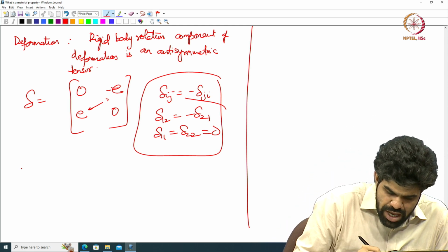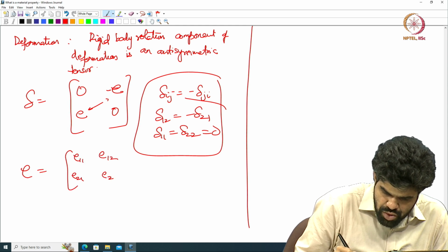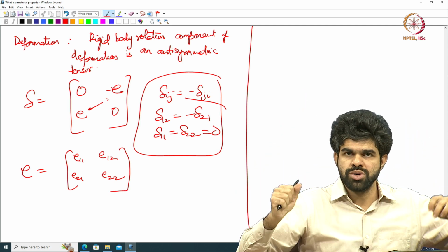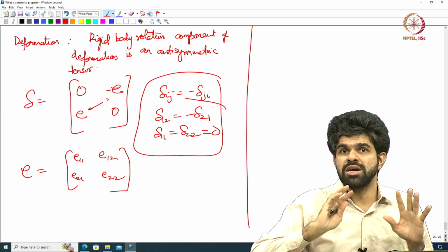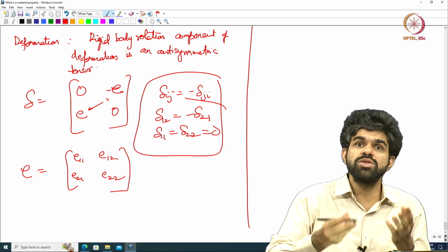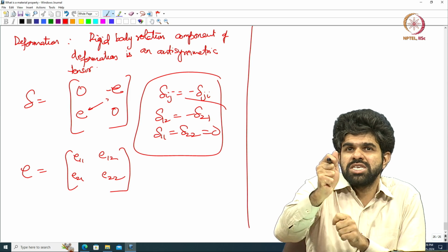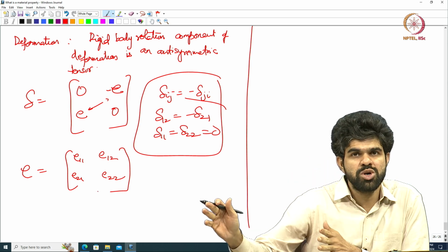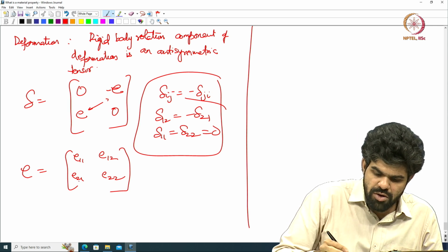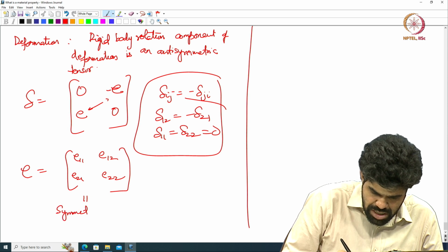Okay. Now, I have a deformation tensor which is E11, E12, E21, E22, right. So, when I deform the material, I can rotate it, I can stretch it and do all sorts of things, right. Everything does not account to straining the material. So, for straining the material, what I should do is remove the rigid body rotation component and keep only the stretching, so deformation minus rigid body rotation is strain. Okay. So, that is where I am going to come to. From this, I am going to write it as a symmetric tensor plus an antisymmetric tensor.